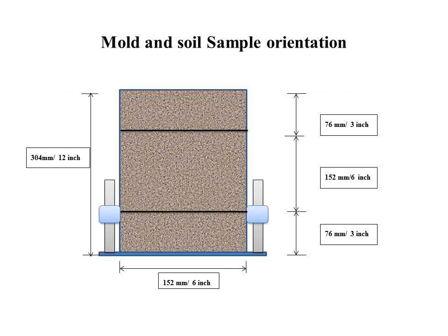This is the mold I used for this research. The height of the mold is 304 mm and the diameter of the mold is 152 mm. The top and bottom layers, that is 76 mm each, are not countable because of soil confinement, and the middle 152 mm is countable for DCP penetration. The soil sample was poured into the mold using the weight volume relationship method at stages of 30 to 100% relative density. The sample was compacted equally and manually using a hammer.